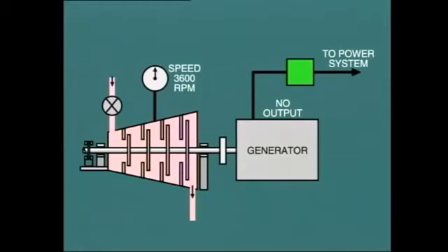Of course, the turbine generator would immediately increase speed because at the instant of the breaker trip, a very large quantity of steam is flowing through the turbine. Under normal circumstances, the governor should be able to close the turbine control valves sufficiently to bring the speed close to normal within a few seconds. However, imagine what would happen if the governor failed to act properly, or the power piston seized, or some other defect prevented movement of the control valves.